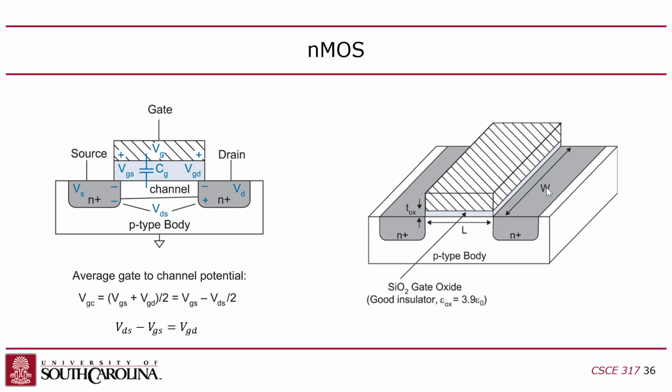And so you want to make this length short so they don't have far to go, because the shorter the length is, the faster the transistor will turn on, turn off. However, there is this additional dimension that you don't see here, the width. This is the width, and the length and the width are actually the gate length and width, right? Although in general, the diffusion areas are the same length and width usually too. But when you measure the length and width, you're measuring the gate, right? So the wider the transistor is, the more area you have to send those carriers across the channel, okay?